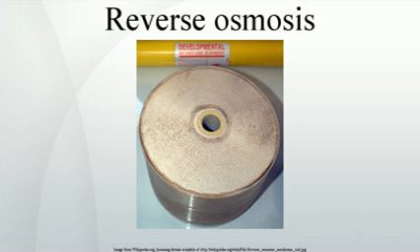A reverse osmosis unit delivering 5 gallons of treated water per day may discharge between 20 and 90 gallons of wastewater per day. Large-scale industrial municipal systems recover typically 75% to 80% of the feed water, or as high as 90%, because they can generate the high pressure needed for higher recovery reverse osmosis filtration. On the other hand, as recovery of wastewater increases in commercial operations, effective contaminant removal rates tend to become reduced, as evidenced by product water total dissolved solids levels.